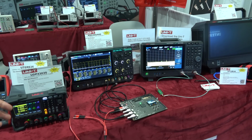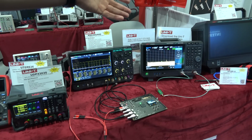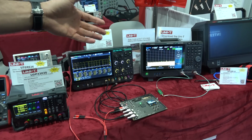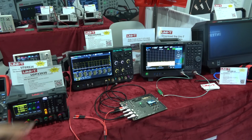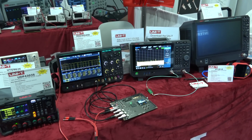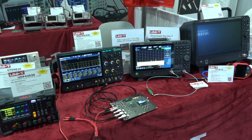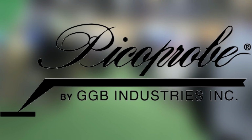But to be able to enter the market and say here's a 26.5 gigahertz spectrum analyzer, minus 163 dBm displayed average noise level, 100,000 measurements a second, and 100 megahertz of analysis bandwidth as the first thing you bring to the market in North America, that's pretty good. So I'm going to be eager to see that. Unfortunately, that doesn't turn on yet because it's going to be released sometime in August. That's just a prototype, but very nice looking instruments, all unified.